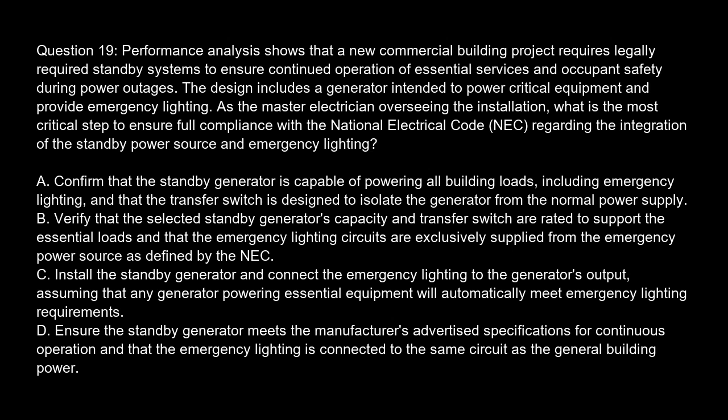Option A. Confirm that the standby generator is capable of powering all building loads, including emergency lighting, and that the transfer switch is designed to isolate the generator from the normal power supply. Option B. Verify that the selected standby generator's capacity and transfer switch are rated to support the essential loads, and that the emergency lighting circuits are exclusively supplied from the emergency power source as defined by the NEC.